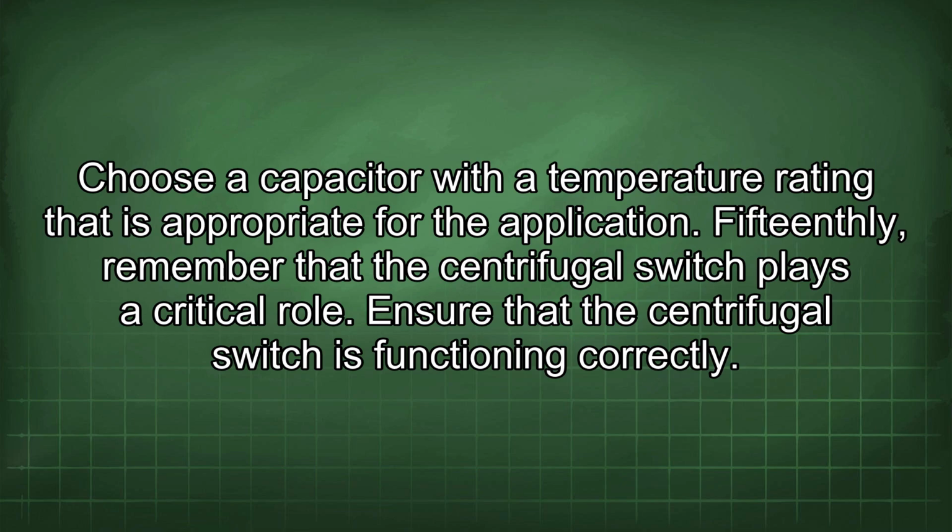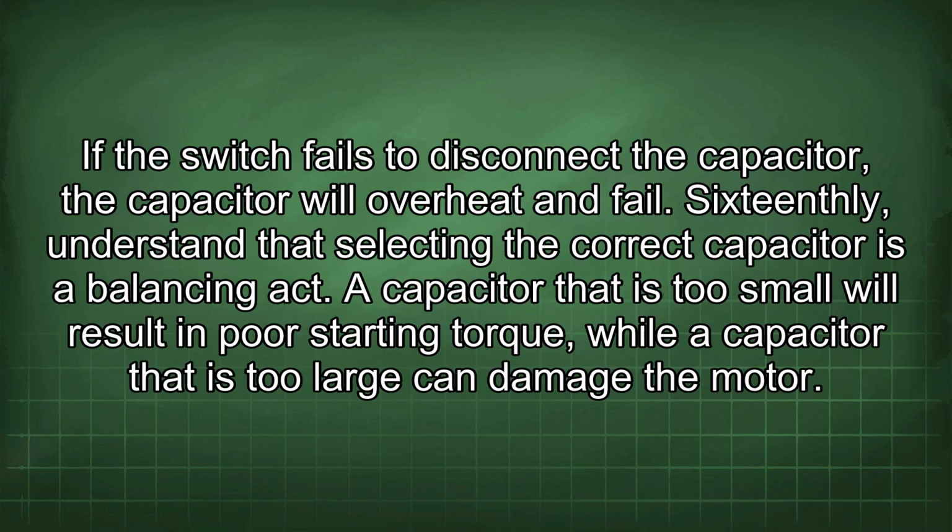15th, remember that the centrifugal switch plays a critical role. Ensure that the centrifugal switch is functioning correctly. If the switch fails to disconnect, the capacitor will overheat and fail.